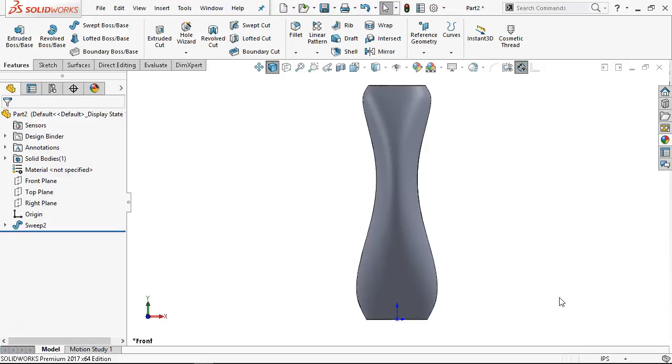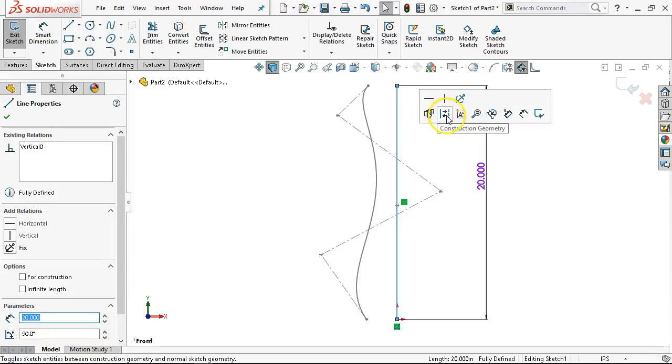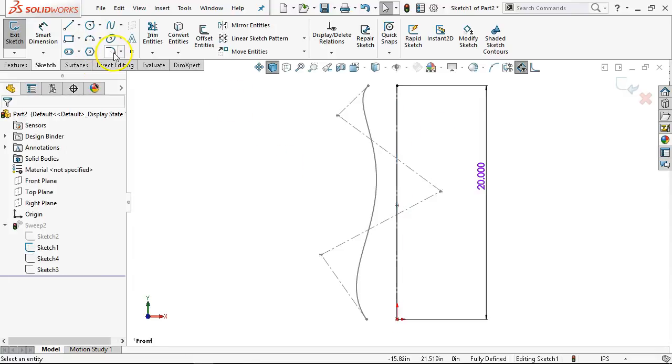All right, so I don't think it's stated anywhere that the guide curves have to go in first, but apparently guide curves should be one of the first things that you start to generate. Figure out what the outside shape is going to be, tie your base geometry to that, and then the path, that straight line, is pretty much secondary there. So the interesting one to try out is if we make that a construction line, and I go back to the spline geometry.